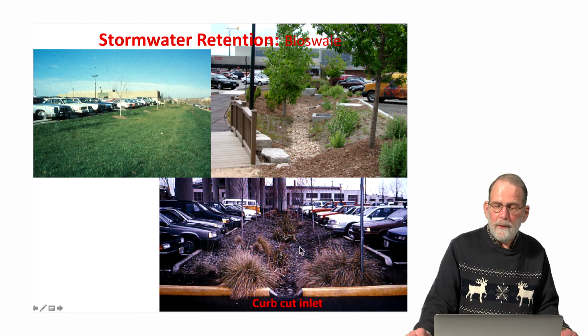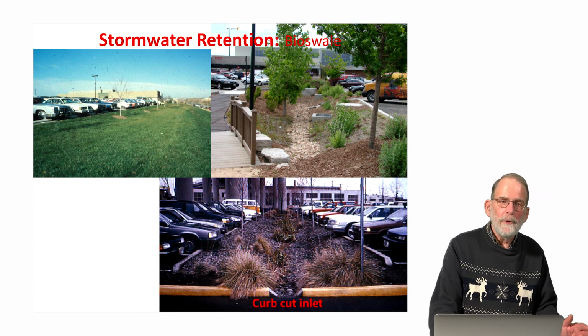Here a gravel-filled bioswale that is helping to capture water coming off of the parking surfaces and infiltrating that water into the landscape rather than having it run off. So again, reducing the rate of discharge, reducing the volume of discharge, and by promoting infiltration and biofiltration, improving the water quality.